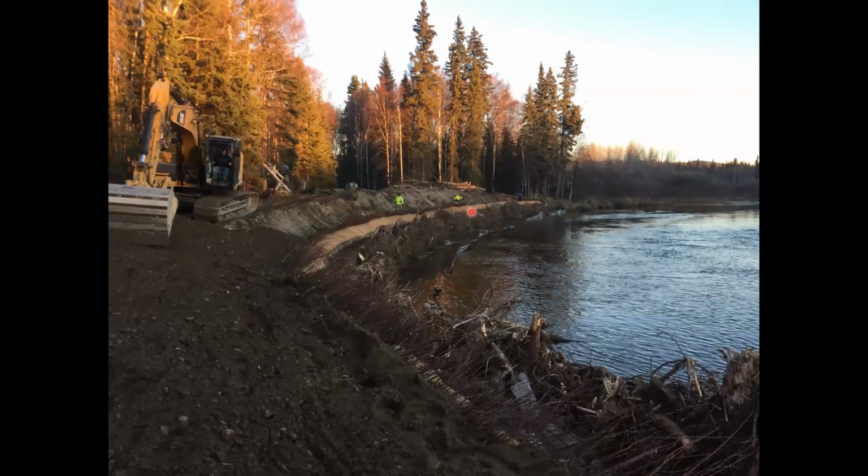So here's a couple more shots. We've got our silt fence in, and then in this particular shot, we're looking upriver. They've put one brush layer in. You can see some willows here. Their brush or soil lift, and then another row of willows. And now they're coming back and just preparing the site for adding a vegetative mat on top.